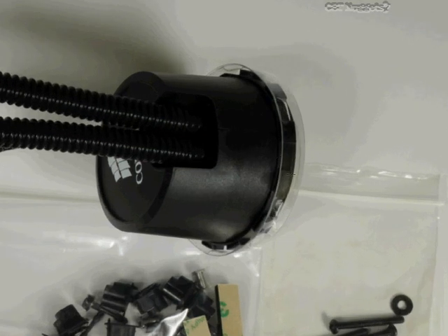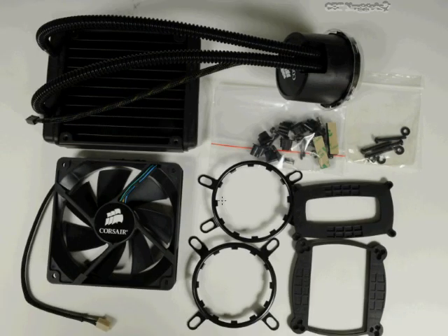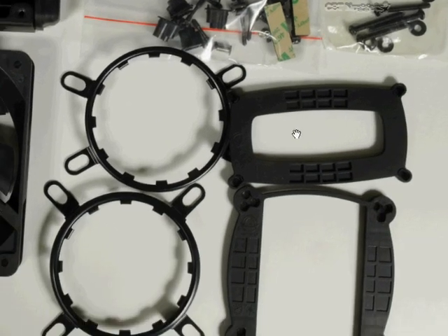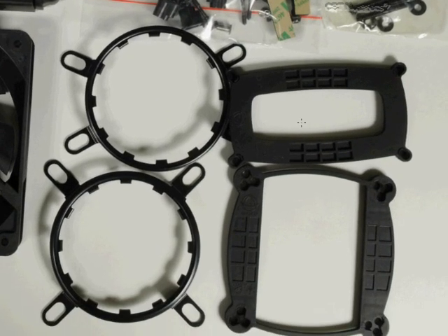Okay, there's actually some thermal grease, which we also can call thermal compound or thermal paste. They're all the same thing, but it's on the bottom of this. It's kind of a gray putty-like substance, and it presses down on top of the processor. Well, the cool liquid that flows through this helps to cool off that processor, especially if you're overclocking, which is what I'm doing here. And then all the rest of this that you see there, these brackets here and everything, these are just a couple of different varieties. Let me zoom in again. A couple of different varieties of attachment devices you can use depending on the manufacturer of your CPU. It's made for multiple different kinds of CPUs that go into multiple different kinds of sockets and so forth.